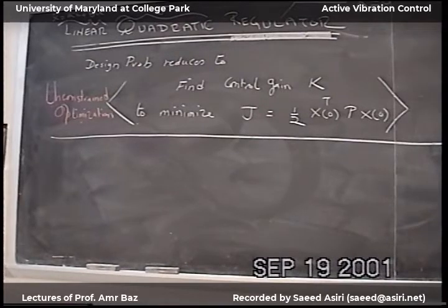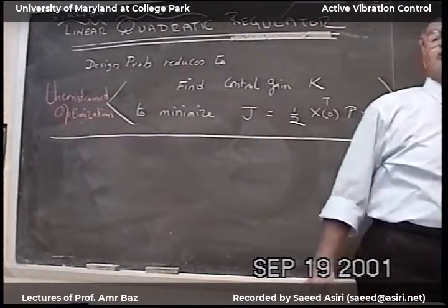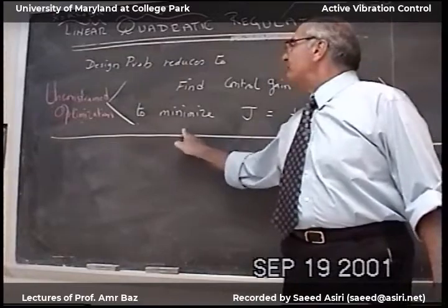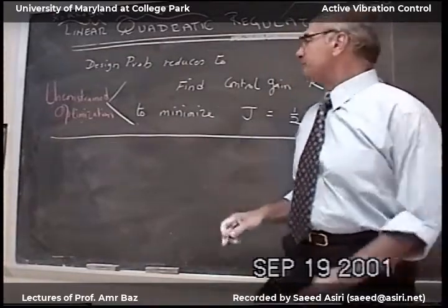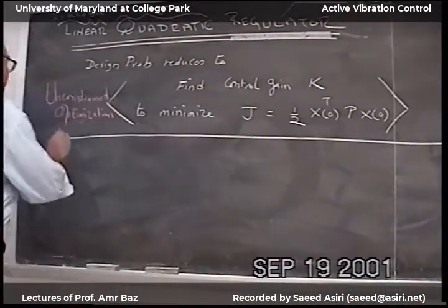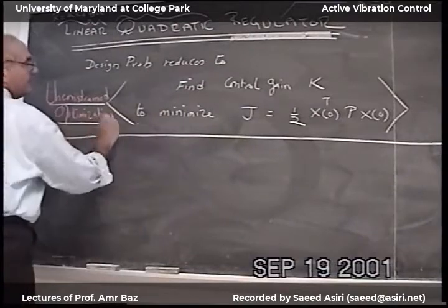So I want to pay very small control effort, so I want to make more penalty on the control effort. So I have to make R large. So I'll bring the U down. Okay, this is one way of getting around this, but there are techniques to put constraint on the U. I'll say here, U should be less than a certain number. Okay, but this problem is unconstrained optimization.